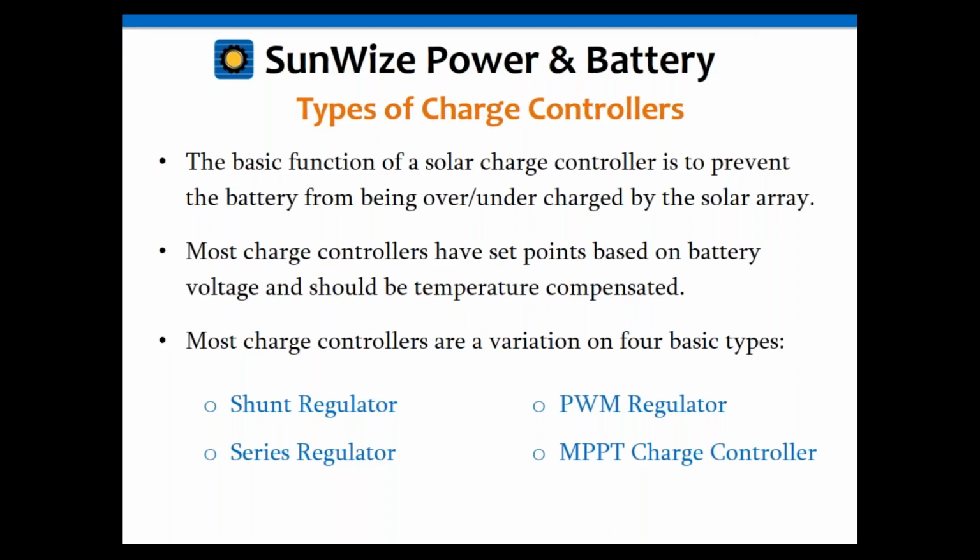Just a side note, I'm always surprised at the number of technical support calls we get where people say their charge controllers have failed, and the majority of the time it really hasn't been the charge controller. It's been something else in the system, either a problem with the solar array or an old battery or a load that is too big for the system. That being said, understanding how your charge controller works will help you troubleshoot your system better. And as the charge controller generally is a central point in the system, it's also a good place to start with the troubleshooting.